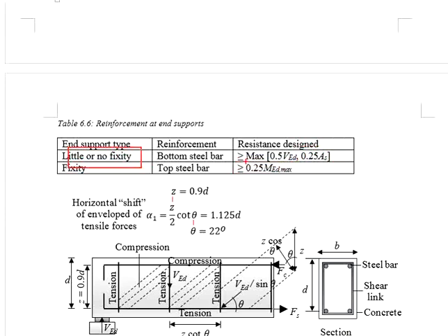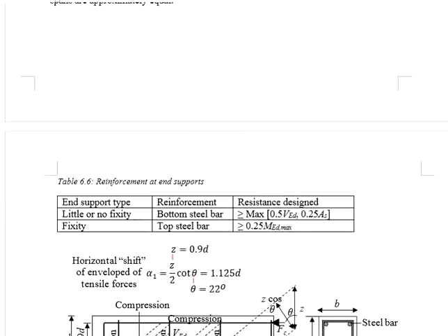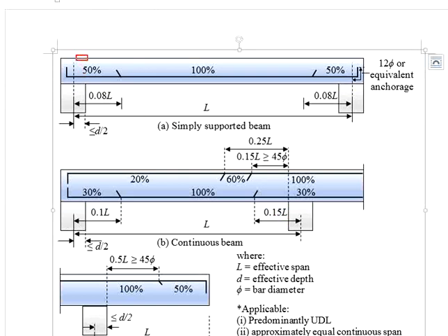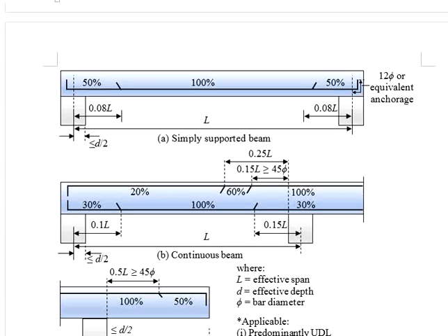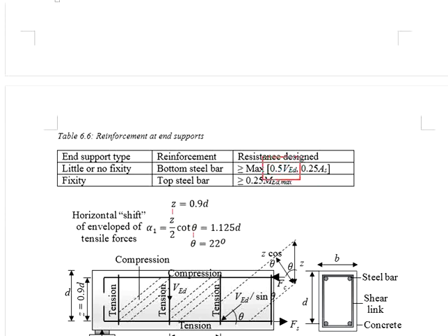Plus, for the simply supported, you need to provide resistance to 50% of the shear loads. Probably you might need to check for this. I believe this is the reason why the simplified method specifies this as the 50% instead of 30%. Although you know that by fundamental, you cannot equate this 50% to the tensile resistance to the 50% of the shear loads acting at the support. Probably you can check on this.